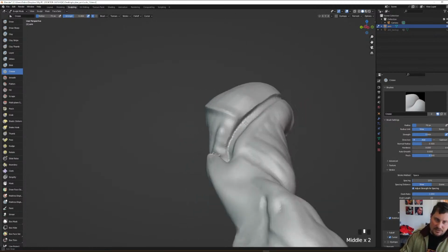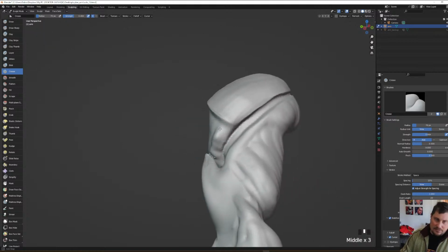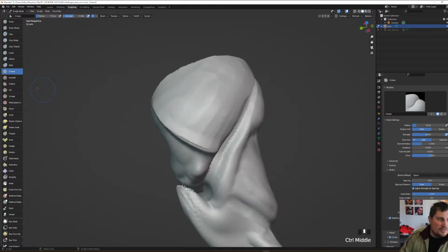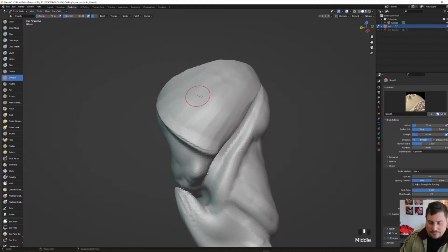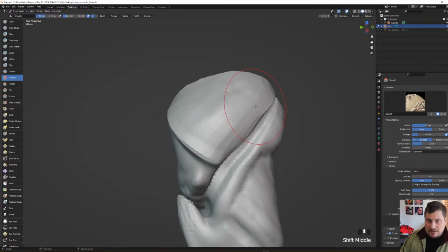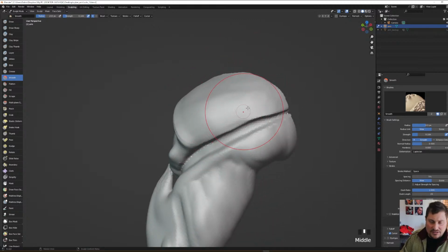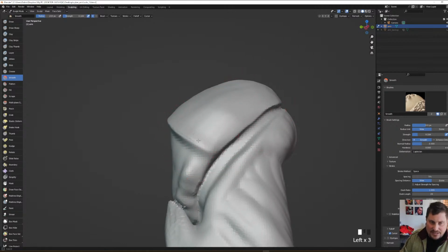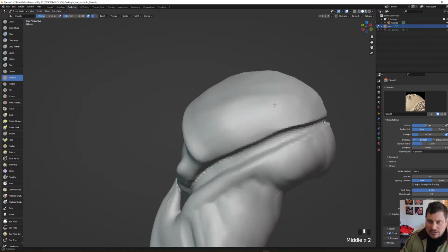And then from here I'm gonna go down sort of straight. Let me grab the smooth brush, F to make it bigger. The smooth brush at the moment has a strength of 0.18, which is just for me to clean up slightly. I don't work with pressure sensitivity because my hands simply don't work that way.